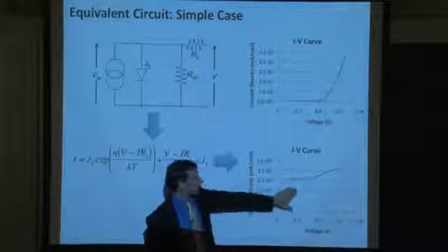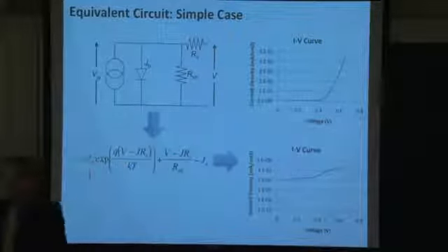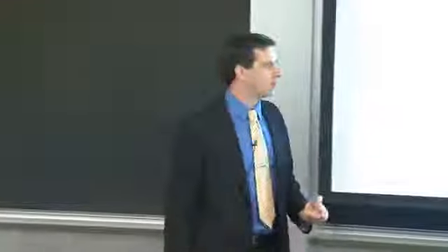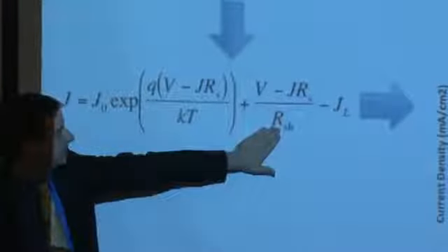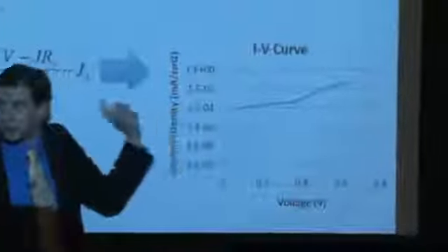And if it finds cells with high shunt leakage current, in other words, low shunt resistance, it will advise the tester and sorter to throw out those cells. And so they'll be put into the scrap pile. The shunt resistance manifests itself right here in the ideal diode equation in this term. It's essentially an add-on term after your exponential. At low bias conditions, you can extrapolate this point right here, determine the slope, and find the shunt resistance.